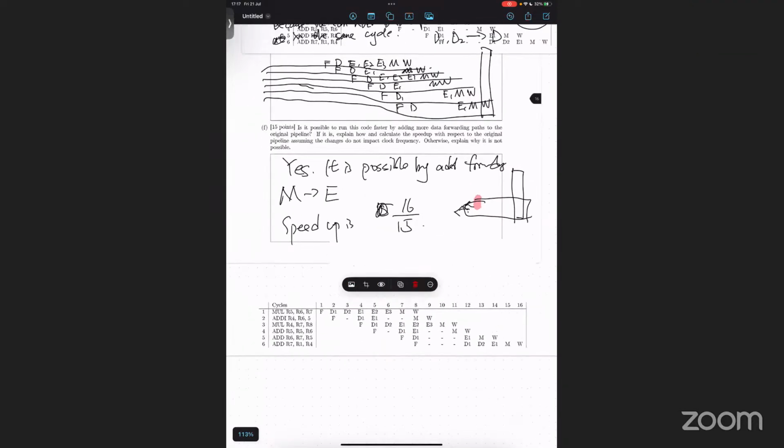So you're referring to the original pipeline diagram, right? Can you say again which instruction you are looking at? Yeah, instruction 2. We are finished with the execute stage because it's an add instruction. But then we have to wait 2 cycles. Yes, it's because it's an in-order pipeline. So you have to wait until the previous instruction has released the stage you need next. Okay, thank you. Yeah, no worries.